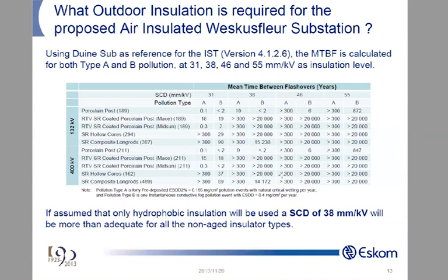The American studies were done where the insulators at 220 kV were not fitted with corona rings. So those insulators were overstressed, and those insulators are failing now. And there's major replacement, and now they're going to go back, or actually move towards glass discs, which suits certain suppliers. And those suppliers are the guys moving around telling you, listen here, you need to go for glass cap and pin discs or coated.